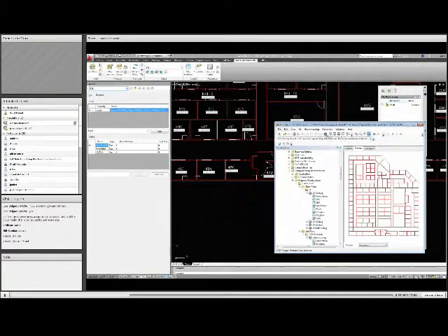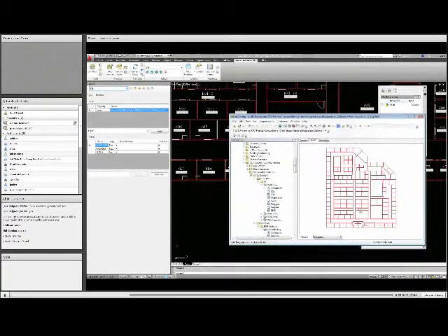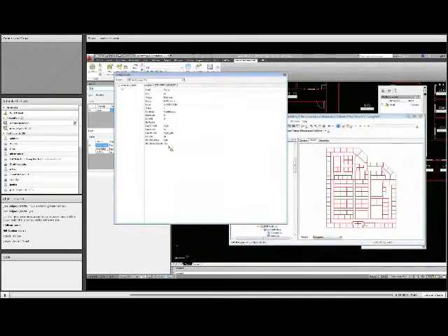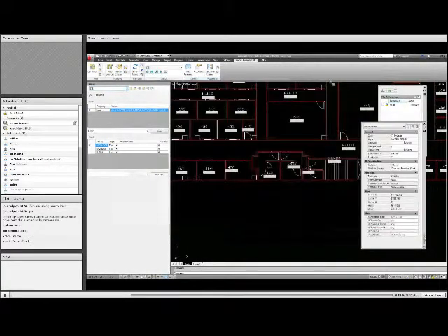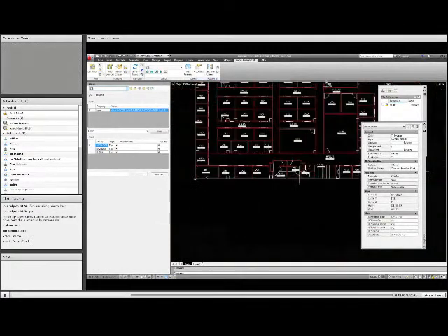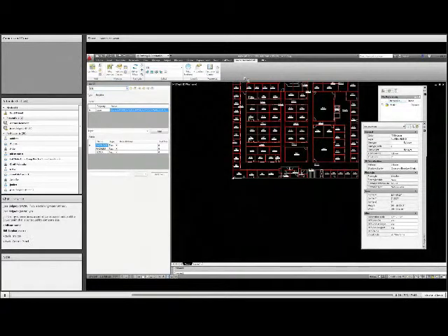This is actually one of my favorites. So I've created a CAD file, and it doesn't have to be anything special. You can do this as a one-time thing. You don't have to save this at all. I just like to have a saved file that I can reference whenever I want to. There's really absolutely nothing in this file. And what I'm going to do is xref in my floor plan, or my site plan actually, first. And there's my site plan.